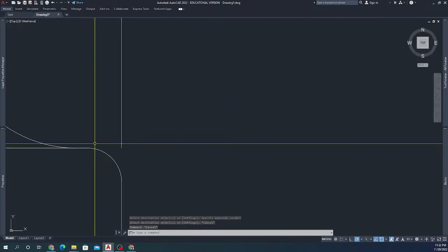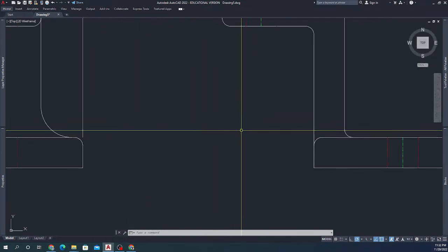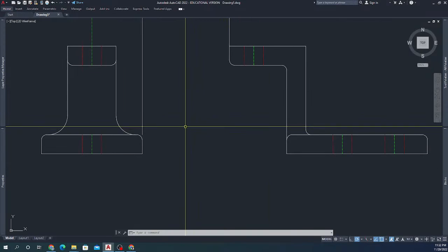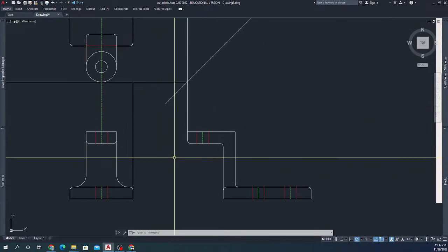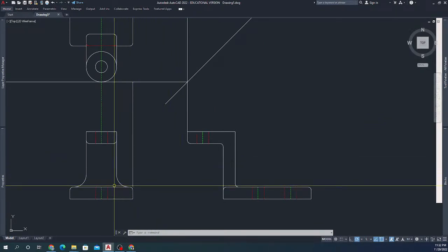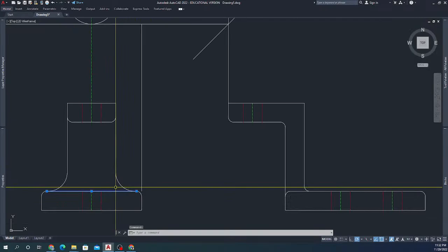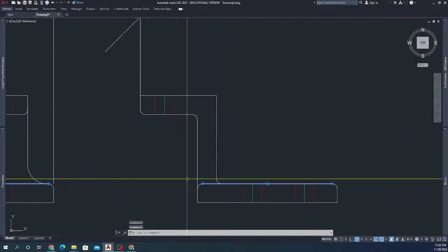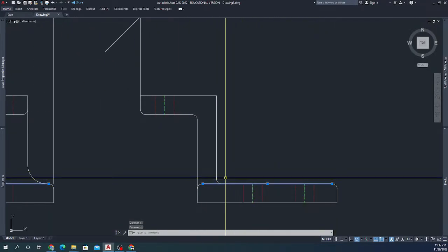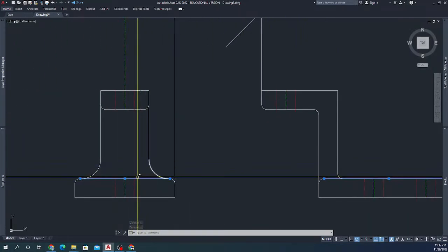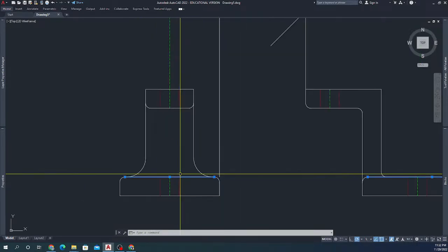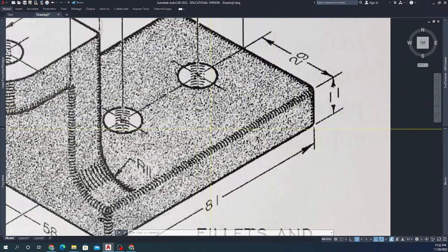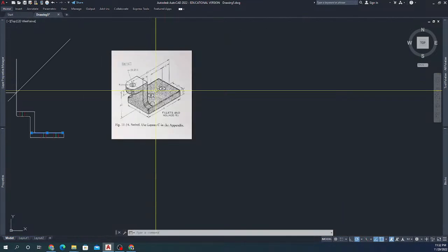So if there is a section of flat surface, for example, the base is flat, and so in this view, we'll continue to see this line because the surface exists for this length. Okay, so we're showing that line continue. Even though it's filleted and everything's tangent, this line stays to show that this entire surface is here and it's flat and it shows up as an edge from those 2 views.